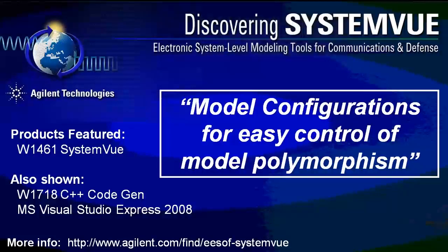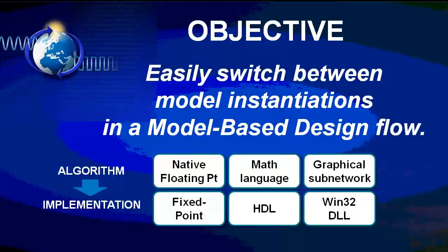Welcome to SystemVue. This demonstration will look at how the Model Configurations tab can be used to easily control model polymorphism for verification using the base SystemVue platform. We'll also show how the Model Configurations tab is integrated with the C++ code generation and Visual Studio.